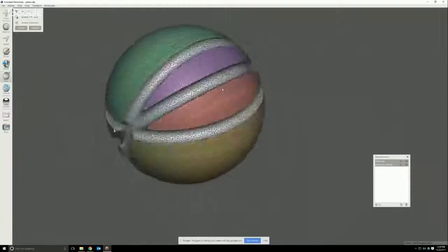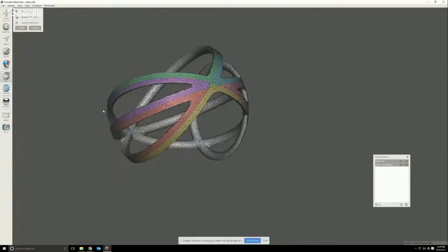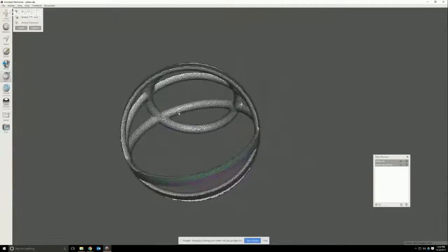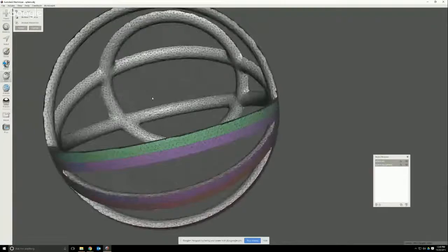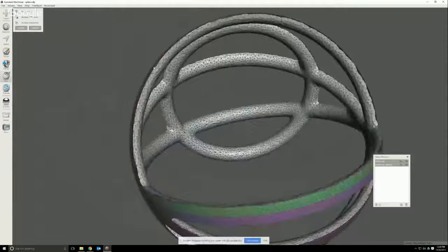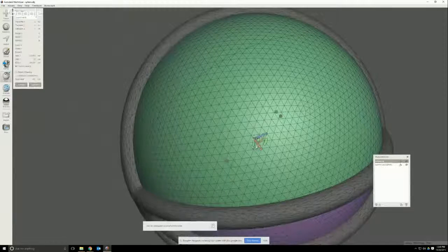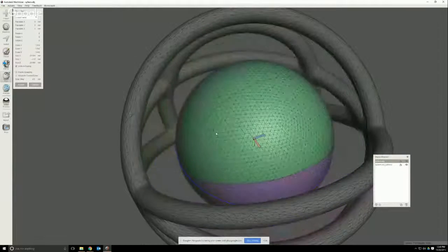Super awesome. Or if I click on Boolean intersection, we get only where that object intersected with the sphere. So the outside of it is smooth, and the inside, essentially, you've cut this in half. This is where it intersected with the sphere. If you go back in, you can do things to the sphere. If I transform this and use this little white dot in the center, this little cube, and click and drag on that, I can make the sphere smaller or larger.